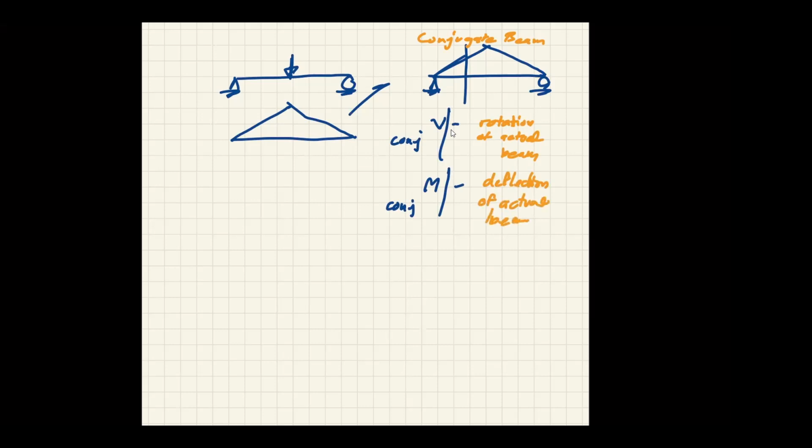So it's kind of good for simple beam, because if you want to use it for the cantilever beam, more restrictions will apply. Okay, so like this, because say if you want to use the conjugate beam for a cantilever beam, this guy has a bending moment diagram like this. So conjugate beam, because a moment is equal to deflection, you have moment here, but the deflection here is 0, right?